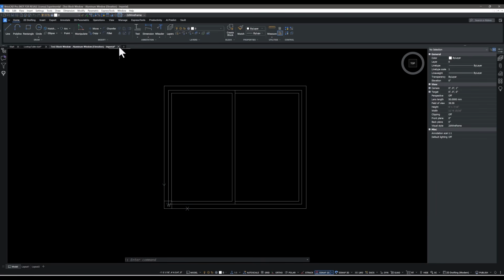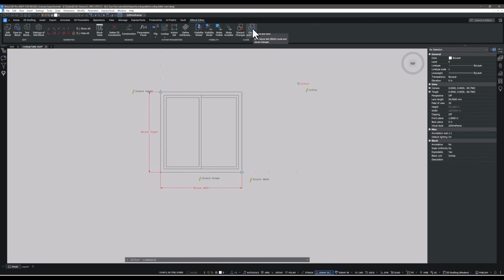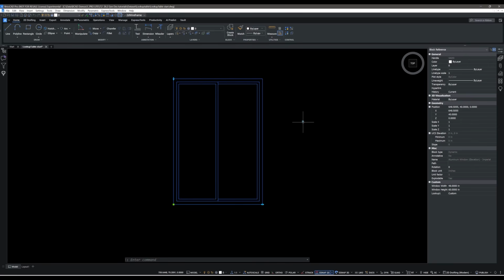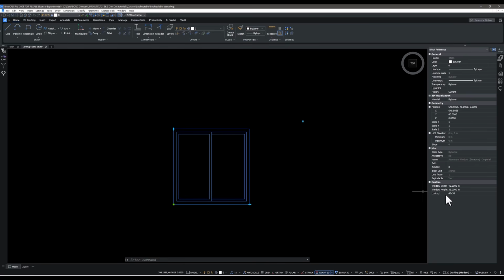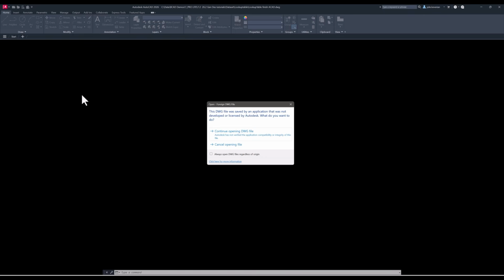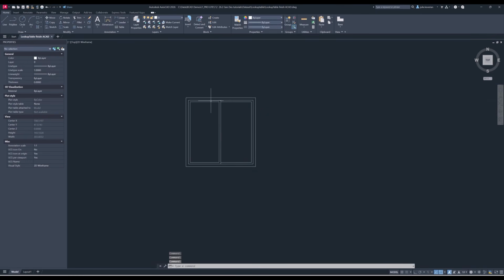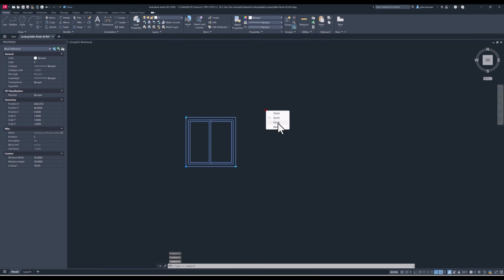That's all good. Let's close the test block window, close and save the block, and here it is in model space. Lookup tables created in BricsCAD round trip into AutoCAD, as seen here. Here's our dynamic block of the window. Now the grip is slightly different, but the information is the same. And the lookup table also displays in the Properties palette.